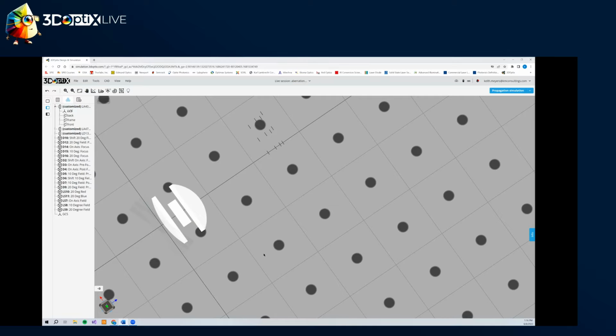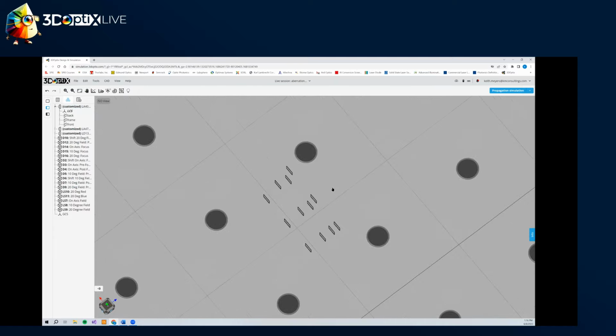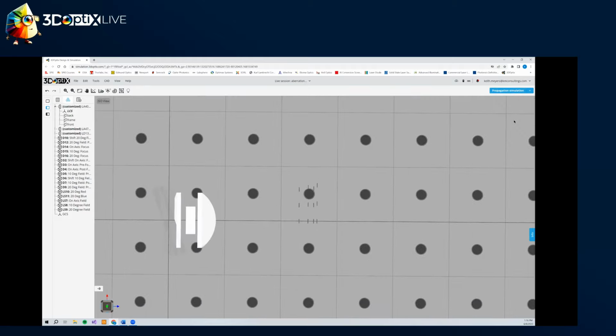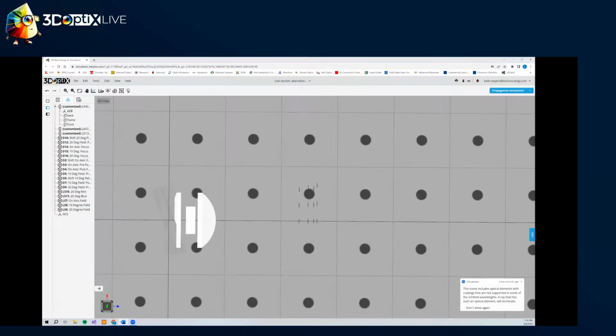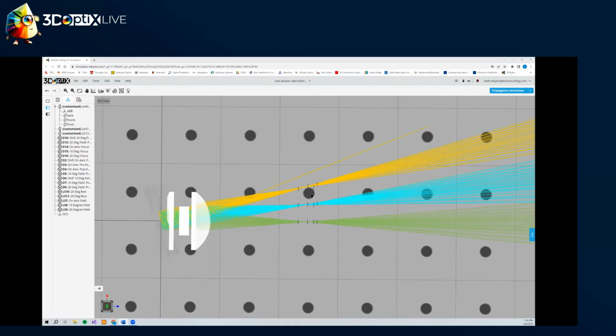Okay, so let's move on to the detectors. So we have some detectors over here, and we're going to use two configurations. It's currently in the first configuration. In the first configuration, we're going to be using the lenses along this line and this line. So basically columns 1, 2, and 4. If we hit the propagation simulation button up here, this will propagate the rays from our system. All right, so now we've launched all the rays. We have one errant ray coming over here. That's going to propagate out of the system, so I'm not too worried about that guy.